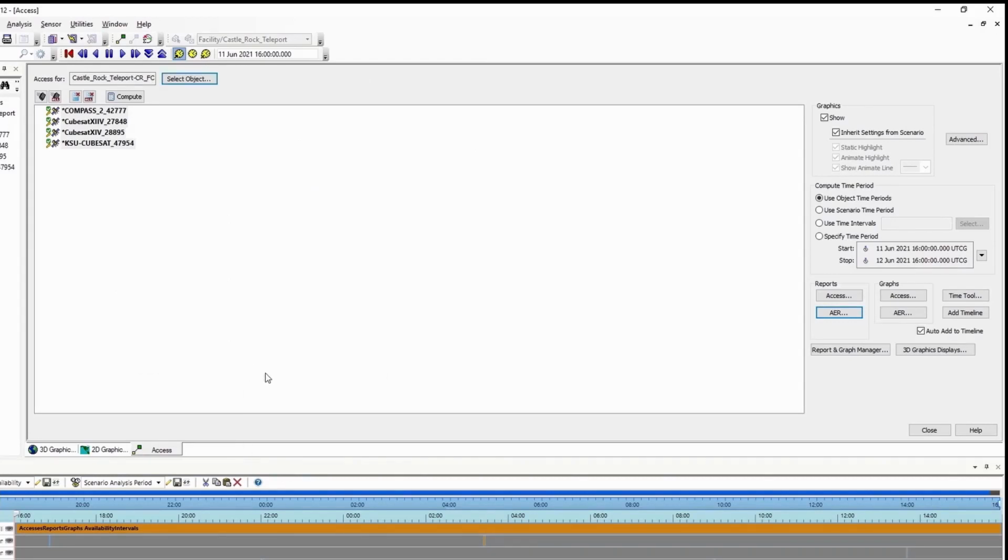There's times when you want to save the original data in a report or a graph because you're going to make some changes to properties. And we're going to do that. We're going to expand our sensor. But I want to not lose my original numbers on my original report. If that's the case, what you need to do is to save a report or a graphic externally.